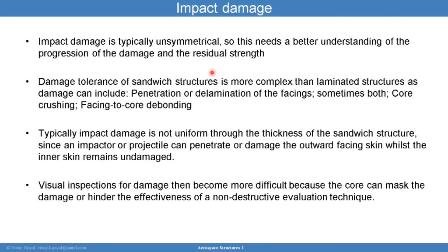And so what we want to make sure is that with visual inspections for damage, we want to find those indicators. And we want to implement impact damage protection plans to reduce impact damage events on composites because of the issues we discussed. And again, it becomes more difficult because the core can mask damage or hinder effectiveness of non-destructive evaluation techniques.